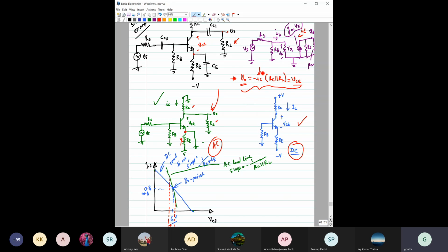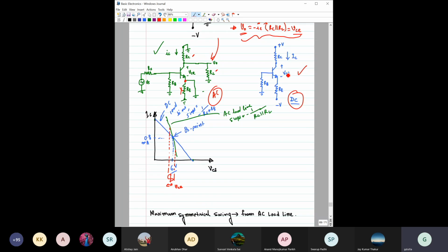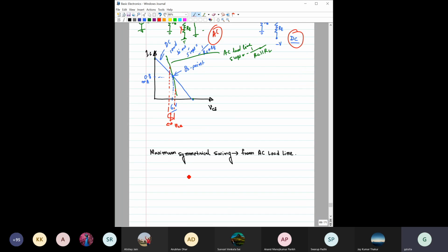IC, we can write it from this gm v pi, right? And for the small signal circuit, you should be able to find the value of gm. The gm value you can find from capital IC, and v pi you can find from this small signal circuit. Right. Now, why I have discussed this, you will understand it immediately here.